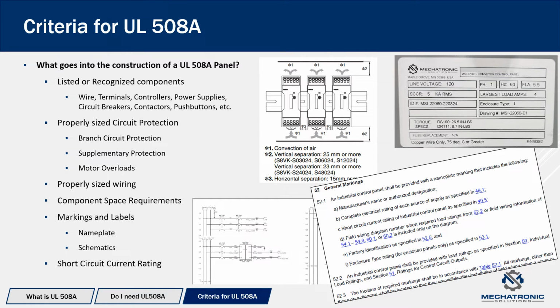We need to show the label on the spool that the wire came from. Like when we have an inspection, a UL inspector in for an inspection, and part of that is because wire is the most counterfeit product with the UL mark.